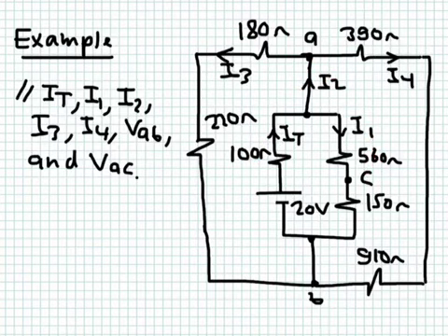two nodes. At first look, the circuit looks scary, a little bit complicated, but actually it isn't. It's actually a very simple circuit. Why? If we realize that this node is the same as this node because they are shorted, and this node is the same as this node because they are shorted, you can see that this branch is in parallel with this branch, is in parallel with this branch, is in parallel with this branch. So we have effectively 4 branches in parallel.